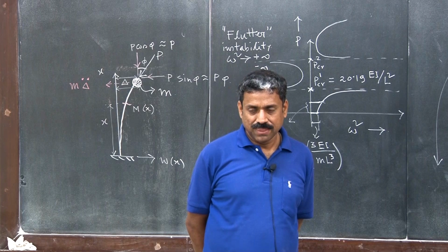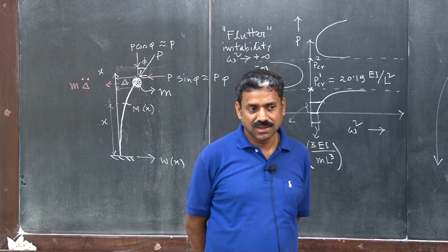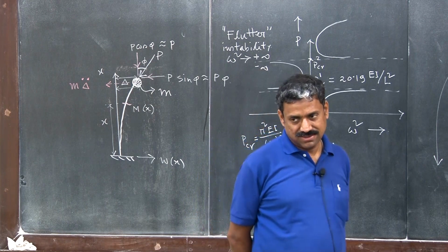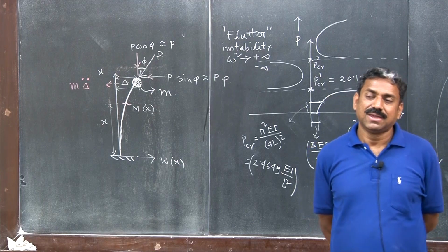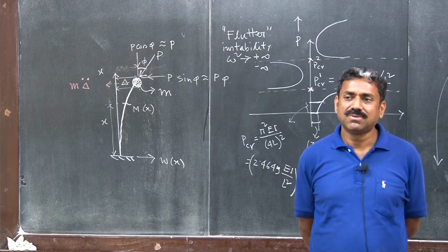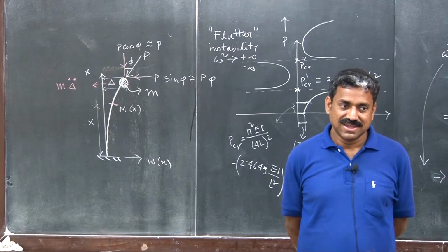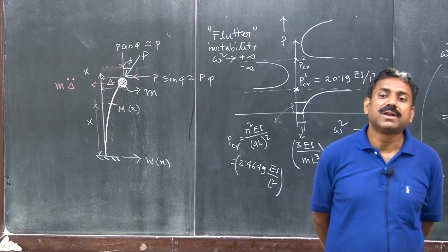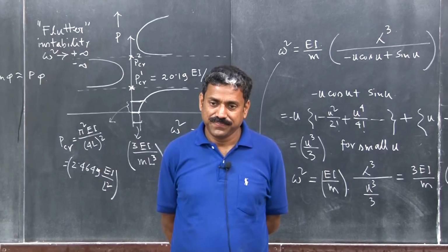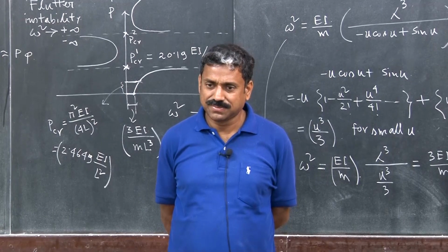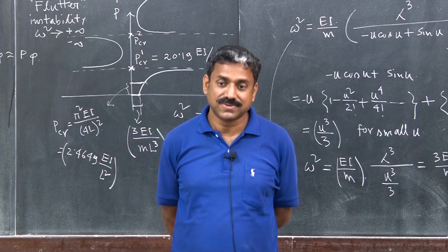Isn't it? So if there is no stiffness, what will be the frequency? If you consider a column which is subjected to axial compression, no follower force, and the load is below the critical load for buckling, then still there will be some stiffness. But with increasing axial compression, its stiffness erodes, right?